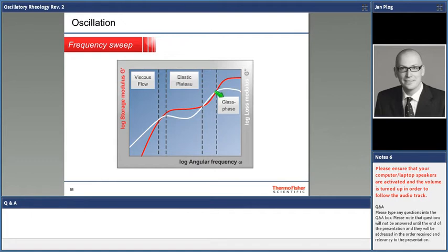When you choose the frequency, the speed, high enough, your system will not be able to follow, and will behave as if it had become a solid, even if your polymer is in a molten state. This is what we call the dynamic glass transition. So you might want to measure this whole range. The problem now is that the rheometer doesn't let you. The rheometer tells you, no, my measuring range is limited due to two different reasons.